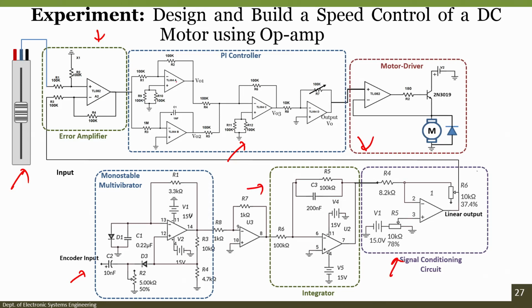What it changes is that along with the proportional term we also have an integrating term. I hope by now you understand the importance of the integrator circuit, and how the PI controller eliminates the effect of the offset error, as well as giving a very fast response. Now, we will see the working of this model.